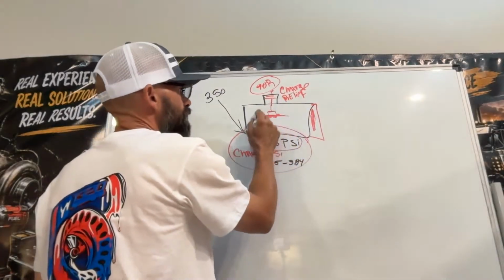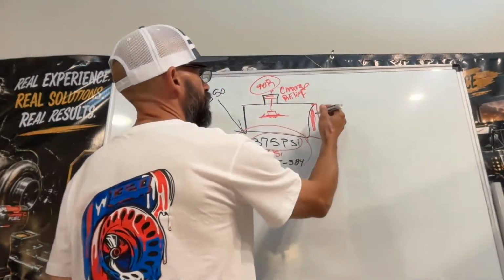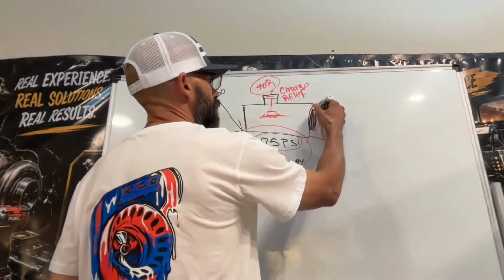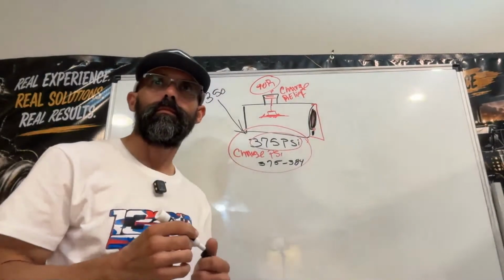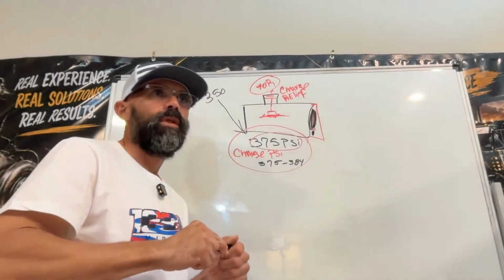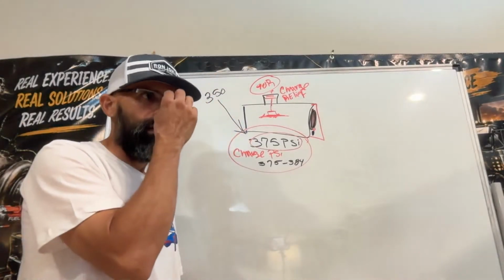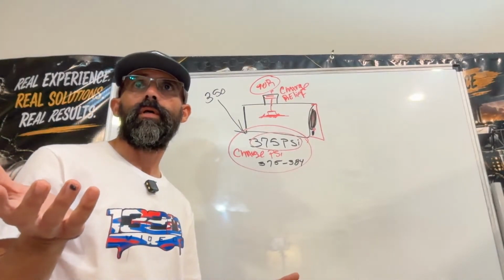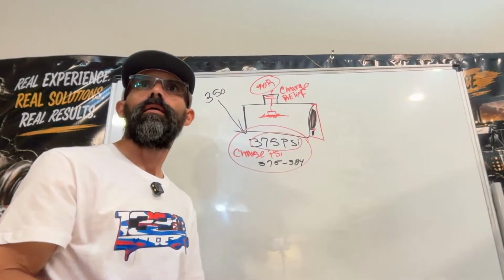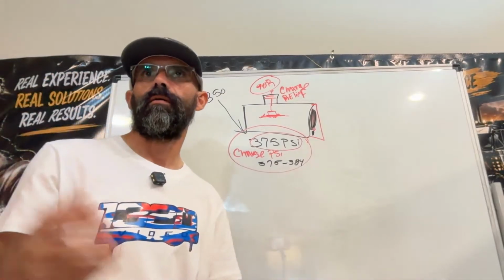So it could be that this thing is getting worn out, but also it could be that the gears right here are starting to wear out, like the oil pump on an engine, right? You see that on a brand new engine on a car or on equipment, you get a high constant oil pressure, let's say 80 psi.